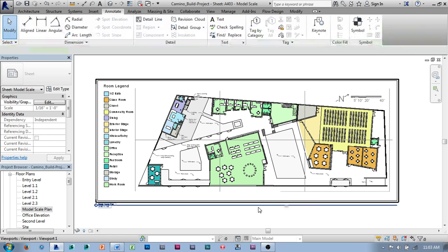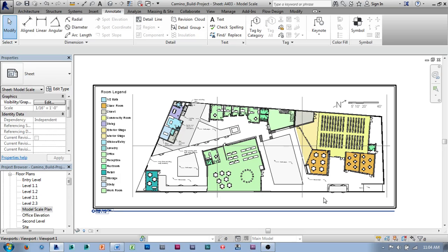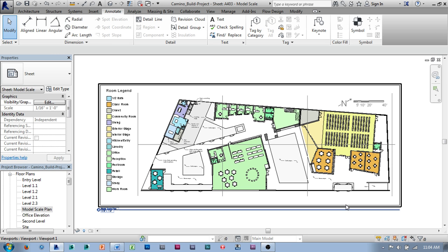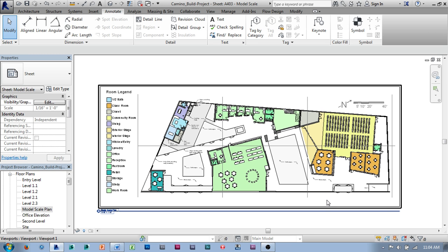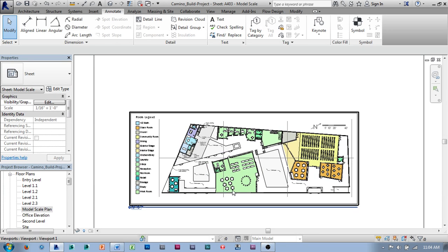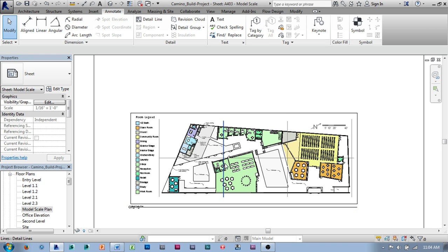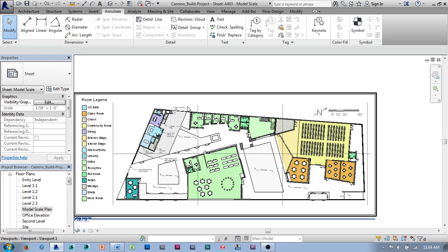The other option I could do is change the size down from a 1/16 to say a 32nd of an inch, and I might be able to get the entire project in the build space, but I would be cutting a significant amount of additional detail out. Going up in size, if I move this up to an 1/8 inch model, I'm looking at a model that's not 1'8" in out-to-out length, but over 3 feet long, which is getting to the point of being ridiculous for a project of this size and scope. So this feels like a pretty good established setup to me.